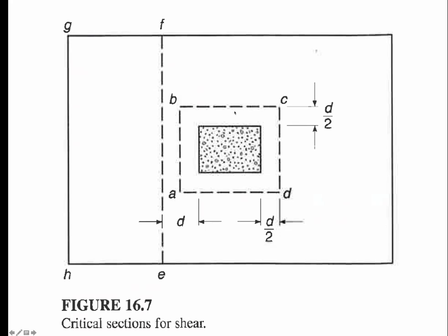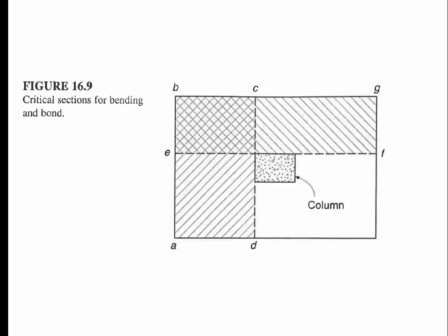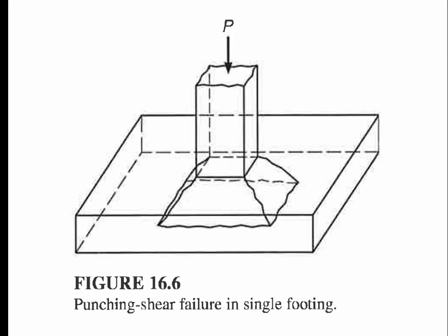It is simplified so that instead of being a 45-degree angle coming off of this column, it's a simplified, I'll call it a cookie cutter version, running right on through the pad of the footing. So instead of this 45-degree shape, we're going to identify some intermediate point out here, a square around the footing that's larger than the column base, nominally something like halfway out.